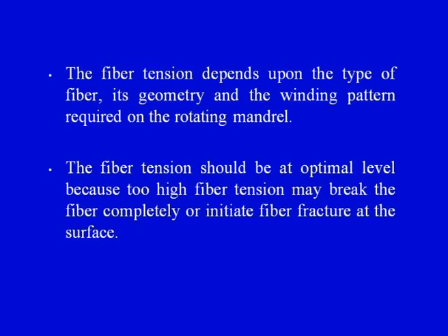The fiber tension should be at an optimal level, because too high fiber tension may break the fiber completely or initiate fiber fracture at the surface. I have already explained that too high fiber tension is also not desirable, because it may lead to fiber fracture or failure of the fiber before the actual winding process, or the surface of the fiber may get degraded because of very high tension. So, we have to judiciously and optimally select the fiber tension during the filament winding